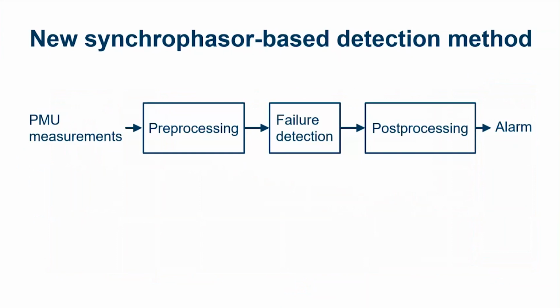Okay. So you all saw the types of signatures that we're trying to detect here, and they're pretty unique and pretty rapid. So it's not a huge challenge to detect them. The challenge is to distinguish them from actual power system events, because you see voltage drops in the real power system related to faults and that sort of thing.